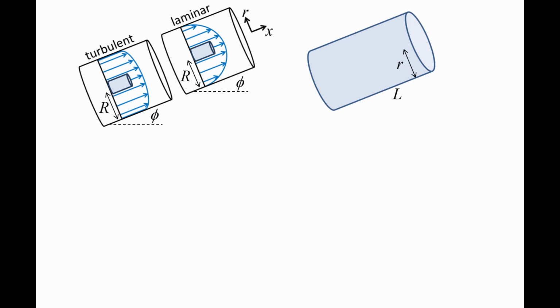There are three external forces acting on the cylinder in the axial direction. First, a shear stress tau acts at the sides of the cylinder due to velocity gradients in the flow. The force due to the shear stress is equal to tau times the area of the cylinder wall, 2 pi r L, and opposes the flow. The resultant force vector is drawn at the top portion of the cylinder for convenience, but the force is actually applied over the entire cylinder wall.